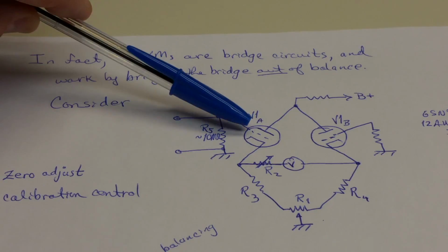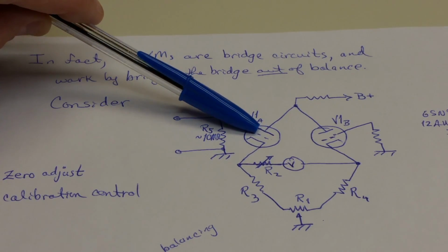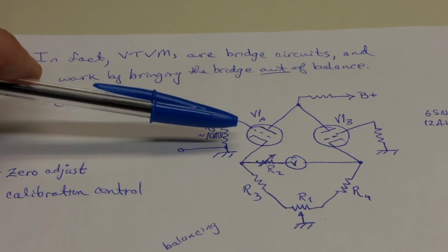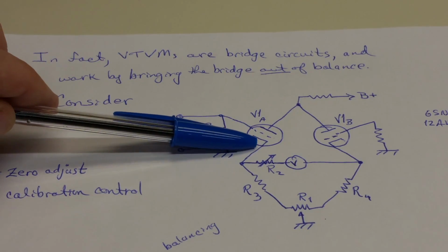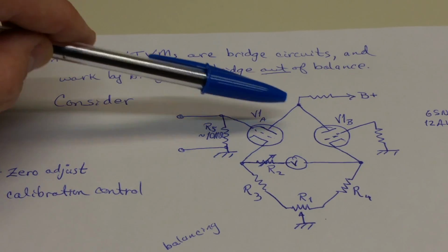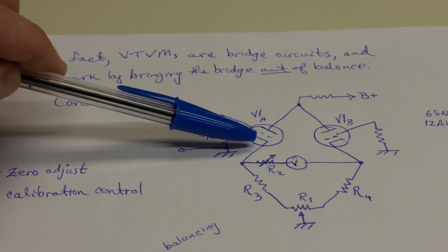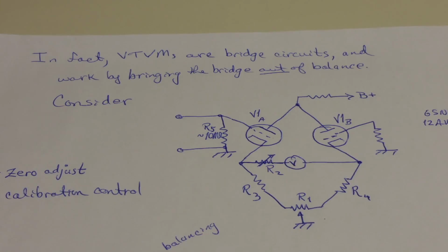Well, what does that do? If I have a positive voltage here adding to the B+ on the plate, I'm going to attract more and more electrons off of this cathode. So you'll see a current increase in the current flowing from the cathode to the plate.